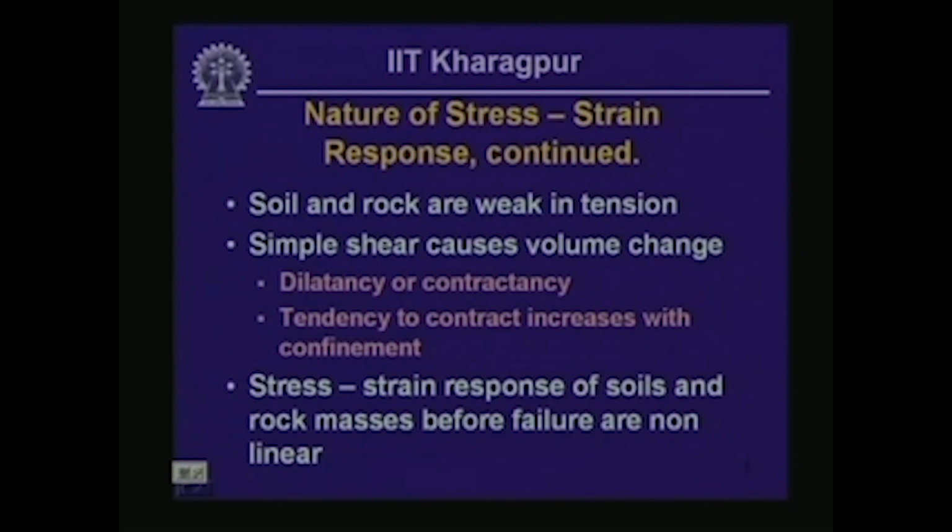Normally, what you would expect is that when you apply shear stress, there is no volume change, whereas when you apply normal stress, only then there is a volume change. But in case of granular material, we tend to see the feature of dilatancy, where when we apply shear stress, the volume also tends to change. We are going to look at the details of this type of behavior in the next little bit.